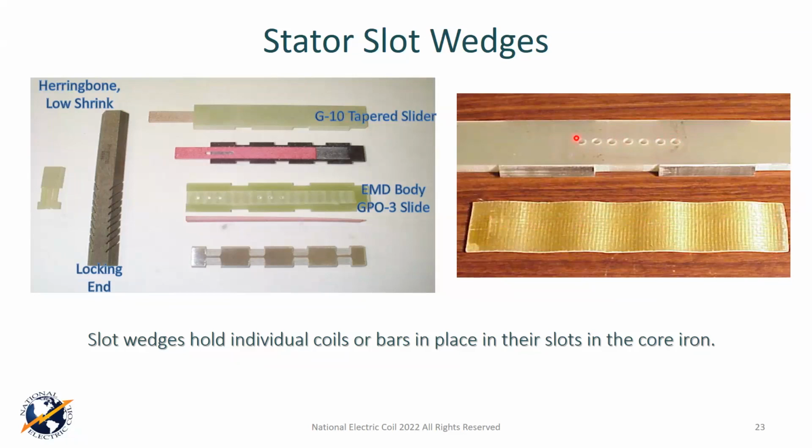And if you chart that and connect the dots, you're going to see how much this ripple is deflected. And if it's 80, 85% flat, and that's what you originally put in, well, it hasn't lost much of its compression, and you're in good shape. If it's baked back to basically what it was, it's relaxed a lot, and you may need to re-wedge and address your filler. So a lot of people call this an empirical way to measure that filler.